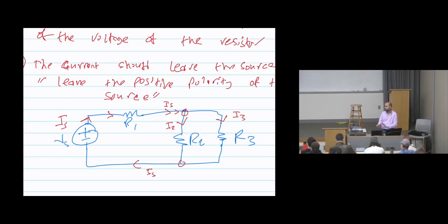Basically, that's how I assume the currents. Okay, does this make sense? It's just easy to follow: out from the source, then it will split. How about the voltage polarities? I need to make sure all of the currents enter the positive polarity of the voltage. So here, I'm going to change the color. Plus minus V1. Why do I make a plus minus V1? I want to make sure Ohm's law is positive.